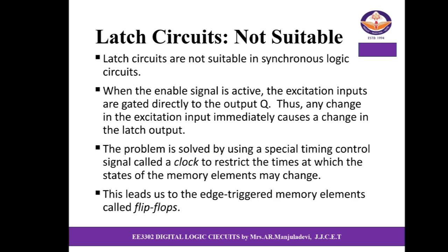Next, we are going to see about latch circuits. Latch circuits are not suitable in synchronous logic circuits. When the enable signal is active, the excitation inputs are gated directly to the output Q. Thus, any change in the excitation input immediately causes a change in the latch output. The problem is solved by using a special timing control signal called a clock to restrict the time at which the state of the memory elements may change. This leads us to the edge-triggered memory elements called flip-flops.